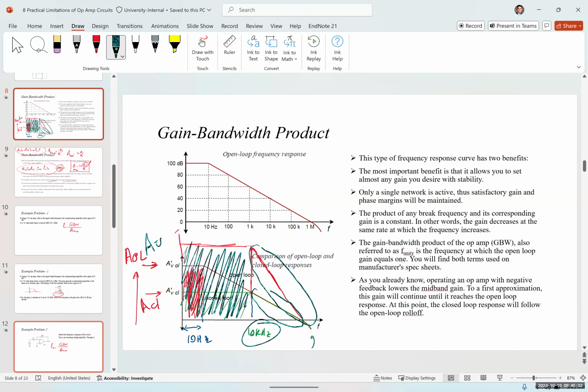Something else is happening here, and it's a drop after that. So here we have a drop of 2 dB. If we have 2 stages, we would have a drop of 4 dB. For example, 3 stages would give us, I'm sorry. 1 stage is a drop of 3 dB, 2 stages a drop of 6 dB, and 3 stages is a drop of 9 dB. I confused the 2 dB drop with the amplitude.